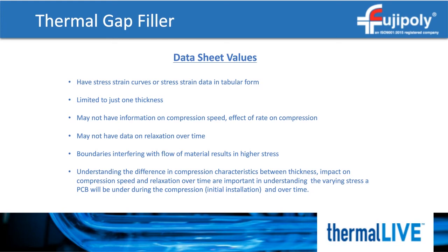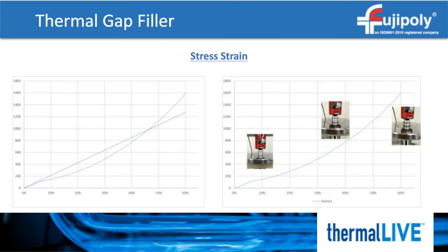On this slide, we can see the stress strain curve of a thermal gap filler. On the right, you can see the platens used to perform the compression testing. As I mentioned previously, the platens are the same size as the pad. There's nothing wrong with this test. It's an actual ASTM test, specifically ASTM D575.